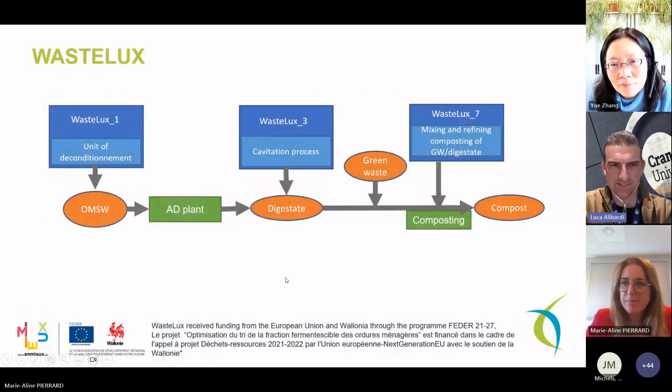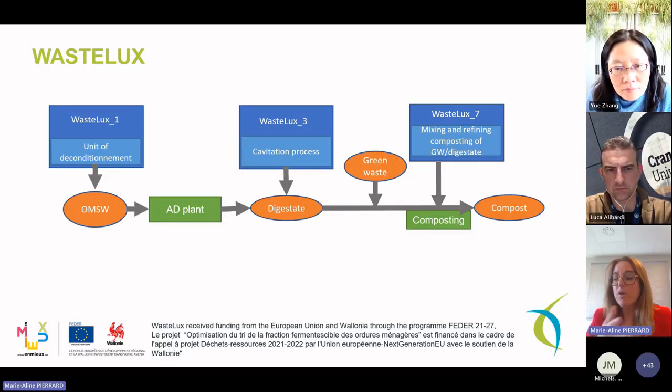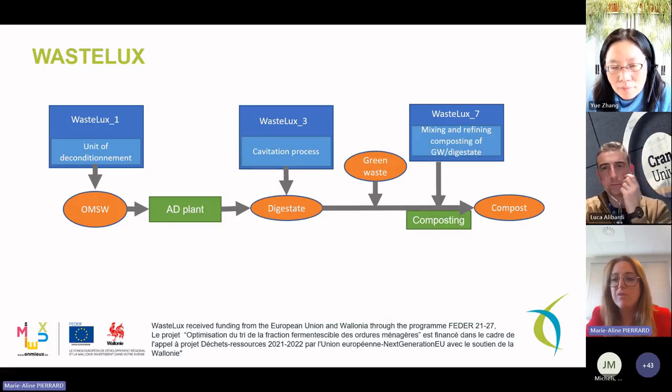Final minute, Marie-Aline, please. Yes, so we are lucky we have a new funding for a project where we want to focus on the plastics. So we have one project working on the pre-treatment of the organic municipal solid waste when they arrive at our plant. Most waste treatment plants have a shredder and a siever. And the problem is when you shred, you sometimes make more pieces of plastics, because the smaller they are, the more difficult it is to remove. So we would like to try another kind of pre-treatment to compare and see if we can remove more plastics.